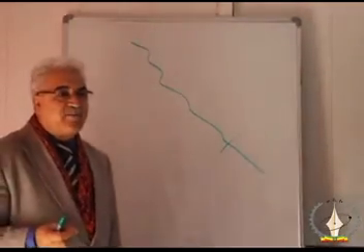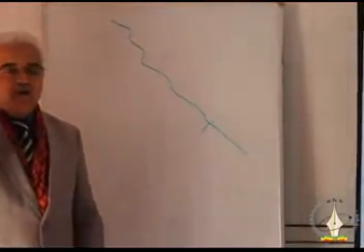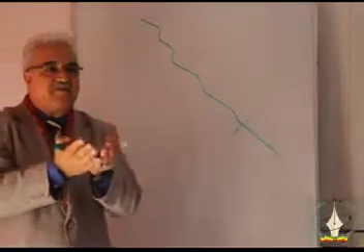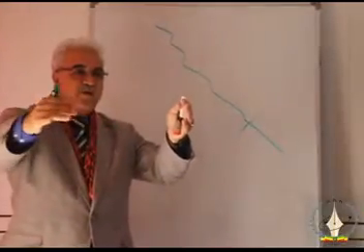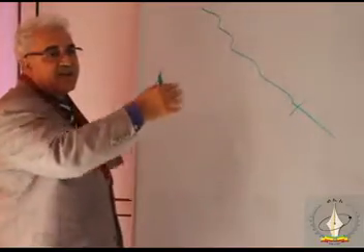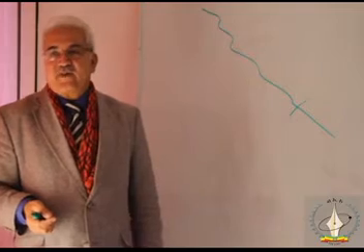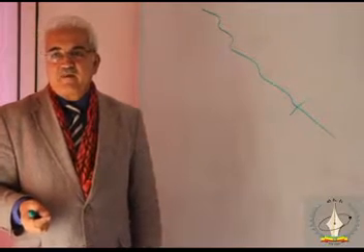What do you look for in the topographic maps? You look for a location where the valley where the water is flowing is narrow, but in the back the valley is large, so you can create a big reservoir, right?